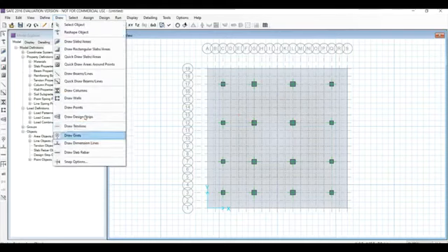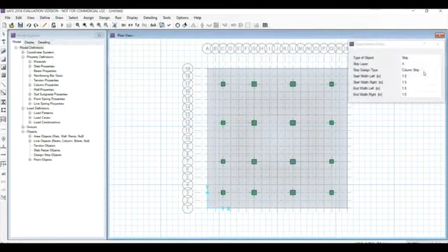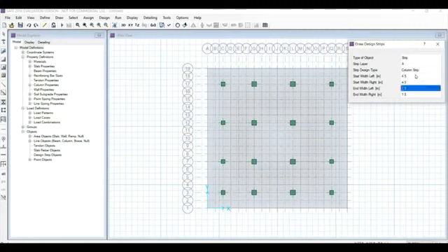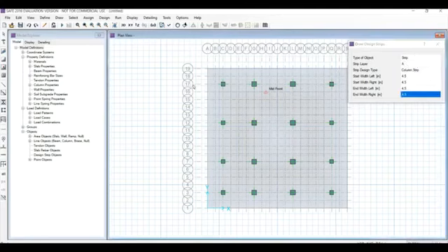For that, draw design strips, and our least dimension is 18 meters, and we need at least 0.25 times the least dimension, and 0.25 times 18 is 1/4 of 18, which is 4.5. So start with 4.5, and again 4.5, 4.5, and 4.5. And now strip layer A and column strip.